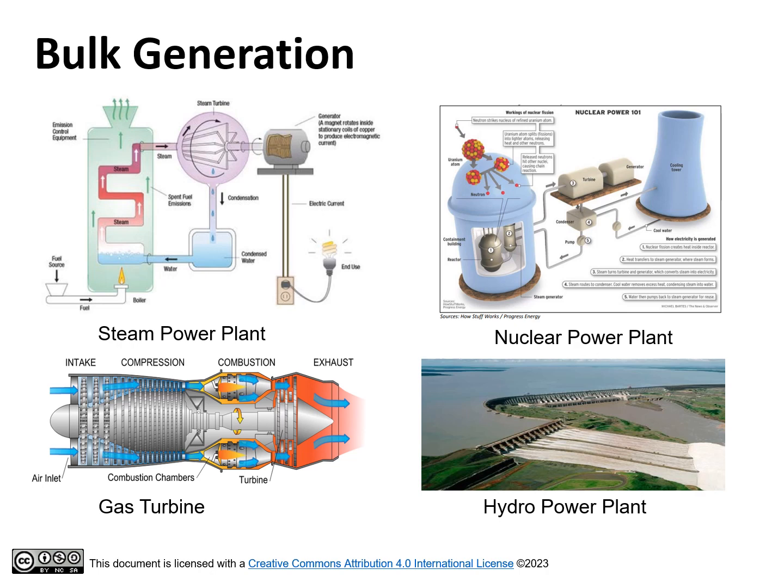Large steam plants are expensive to build but relatively cheap to operate, so they should be run more or less continuously as base load plants. Gas turbines are relatively inexpensive to build, but expensive to operate. They are most appropriately used as peak power plants.